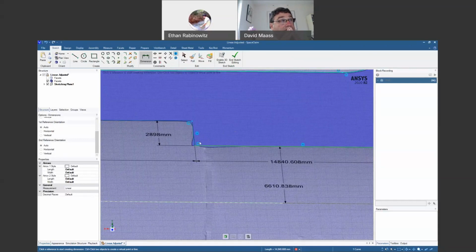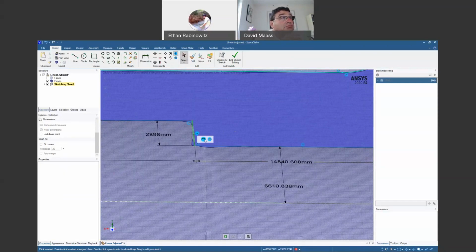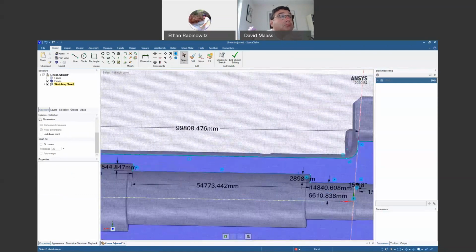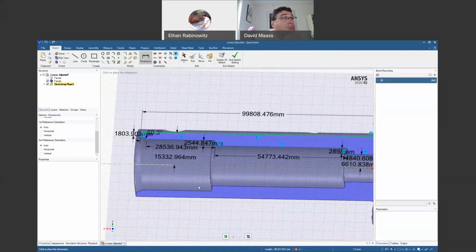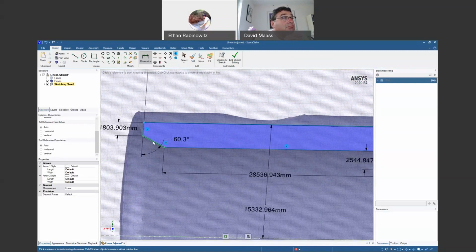Right here in this drop down, so we have the dimensions. That one's vertical there. All right, so we'll throw some more on for like this one down to here for that diameter. That looks good there. Here, I think we either need to give it a length actually, or what probably makes a little more sense, or is more dimensionable or quantifiable, is this dimension, although that fully constrains it.